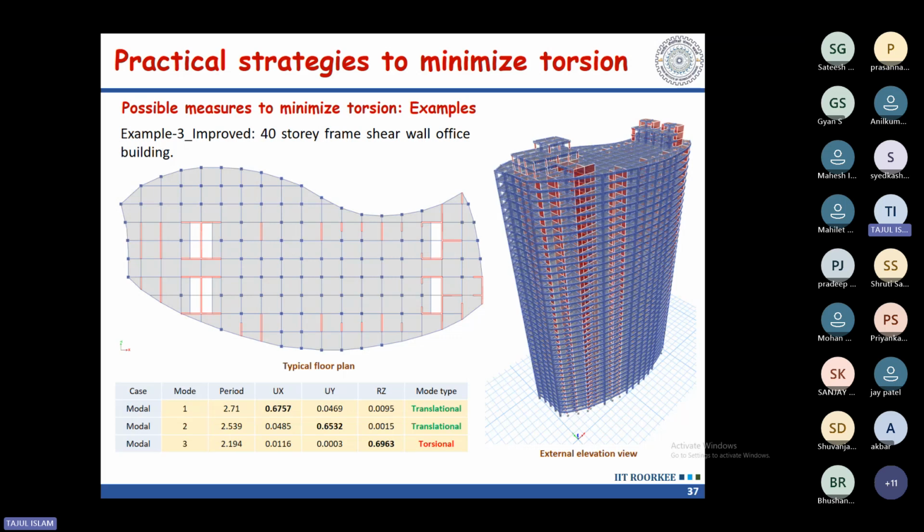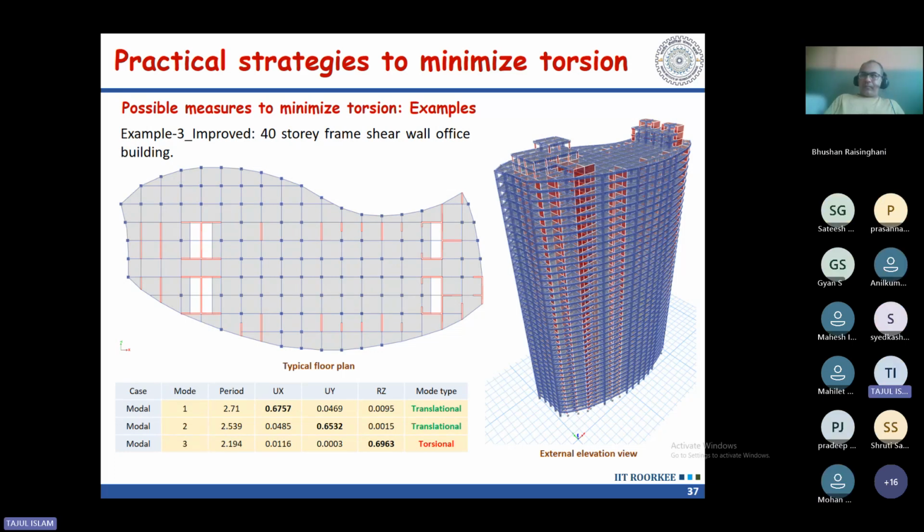Otherwise, you have to go for dynamic analysis and check. Yes, but I'm not familiar with ETABS, but instead we will model it as one model. But whatever mass participation factors we get are for the entire block, right? Yes. So that is not acceptable for whatever configuration you have introduced, like a corridor connecting multiple towers.